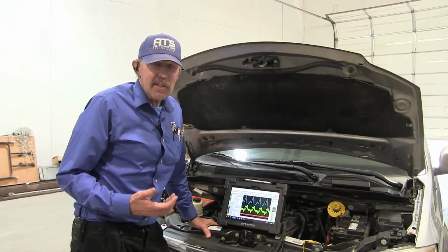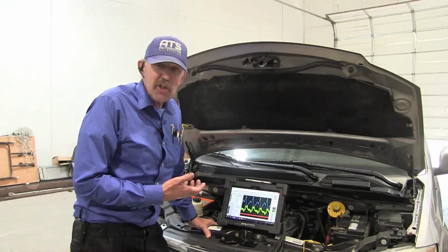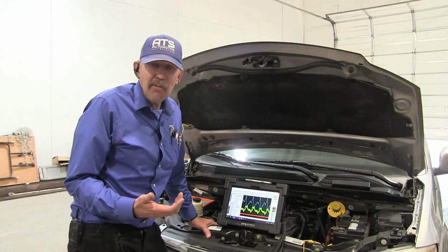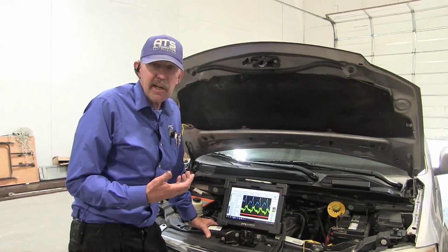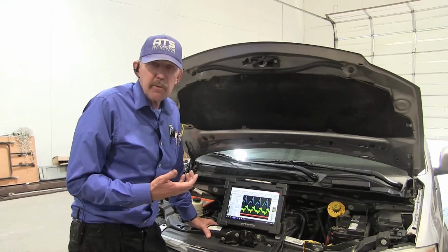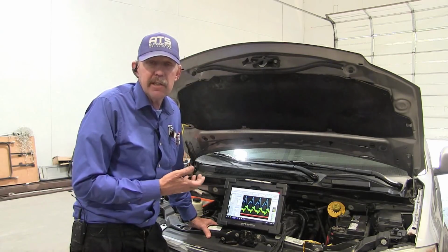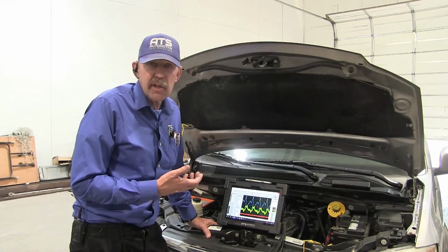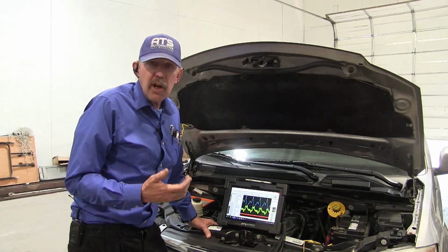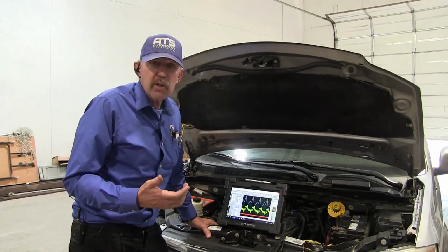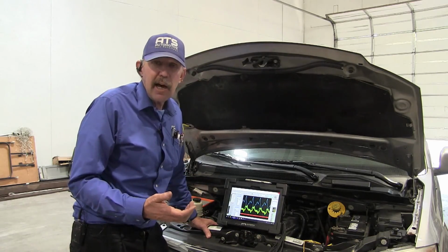Okay guys, is this one cool little Town and Country? This 3.6 is just cool, guys. When he came over here and told me he thought he had a low cylinder and the pressure wasn't any good, I thought for sure it was going to be a rocker, because I've had a lot of problems with the rockers and lifters on these 3.6s. I've seen a lot of issues like that. So here I came expecting one thing, but that's why you never expect what you think you know, because you don't know. Let the data drive the diagnostics.